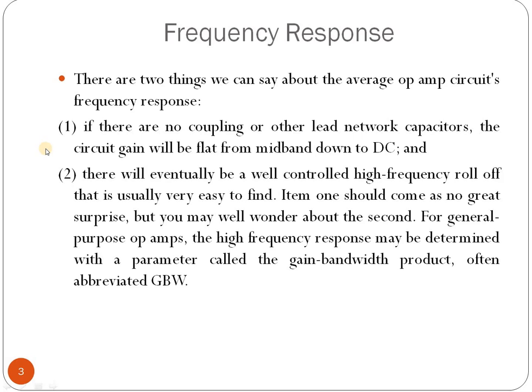There are two things that we can say. If there are no coupling elements or any lead network, something like capacitors, then the gain will be flat. It is not very high. It is flat from midband down to DC, so it will not fluctuate heavily. And for high frequencies, it rolls off, that is, it is sloping.